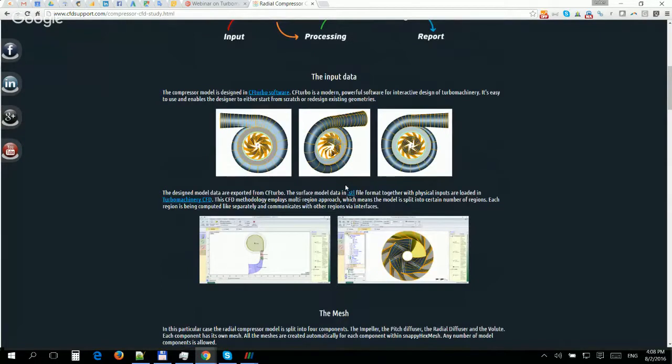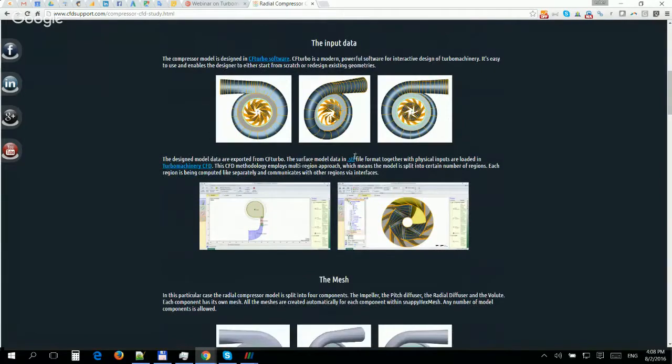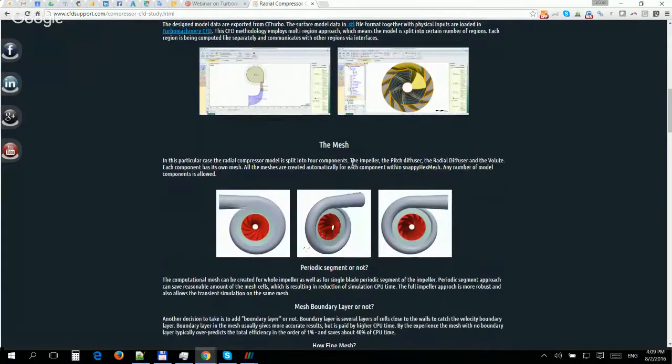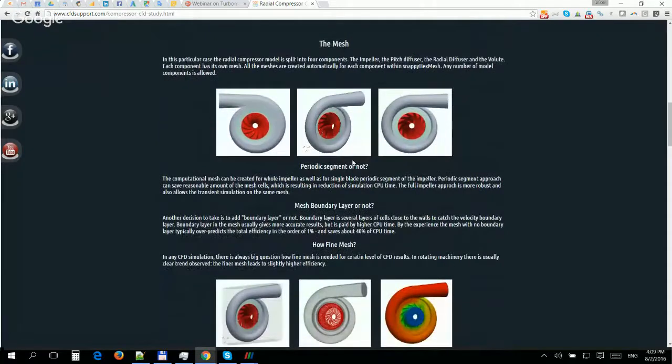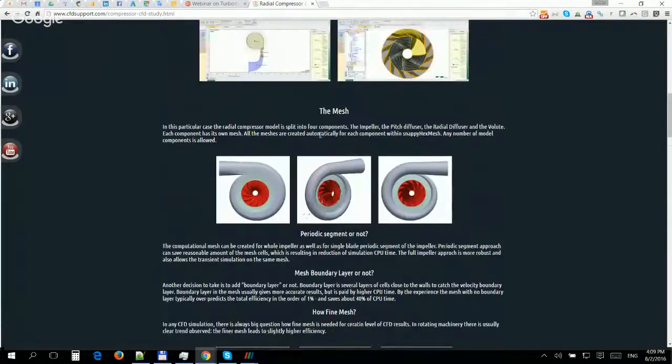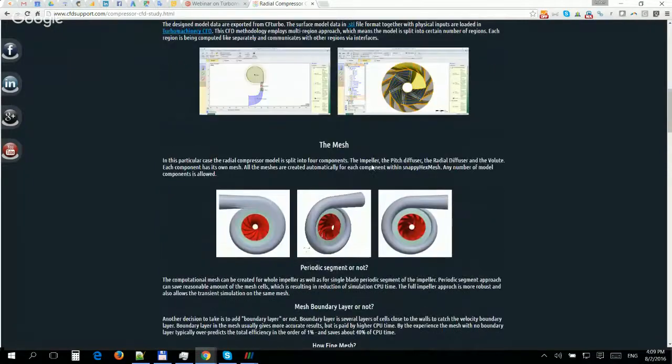Typically, the aim of the compressor designer is hunting for the pressure ratio, flow rates, torques, and of course the compressor efficiency. Each Turbomachinery CFD simulation has its data inputs, and those are the configuration file or the configuration setup in a graphical interface, and the surface model. The surface model is something which comes from the designer, which is the machine which is going to be tested, and then its settings.